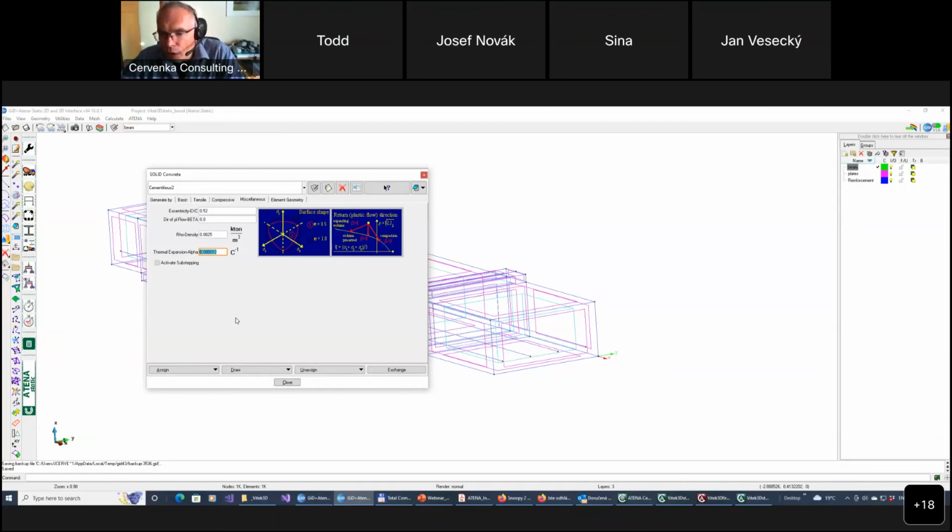Because the spalling actually has two reasons why it happens. One is the vapor pressure in the pores. But the other thing is that spalling is also the result of the pressure in the layer of concrete, which causes a kind of buckling, if you think about it. And this, in addition to this vapor pressure, may cause explosive spalling of concrete.